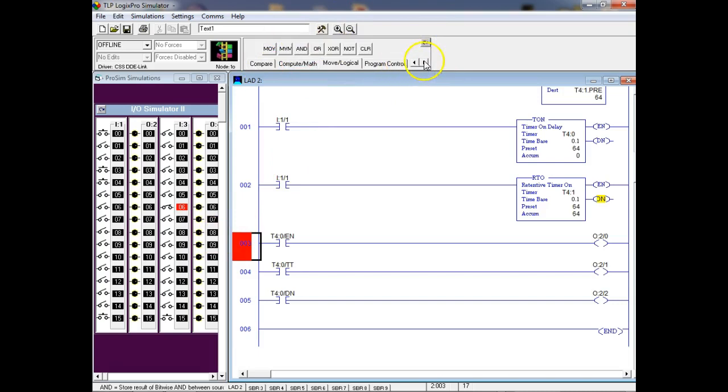So it sounds like using a non-retentive timer uses fewer steps. It is, but you don't keep up with your time. You understand? So there are times where we want to stop and stay stopped for a little while. I'm over there doing something and something happens and I need to stop it. But I need to run this 15 seconds after this.